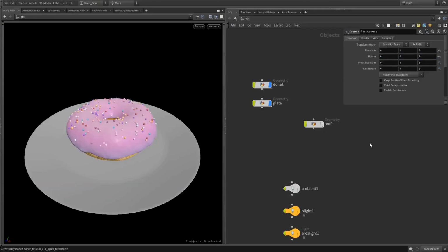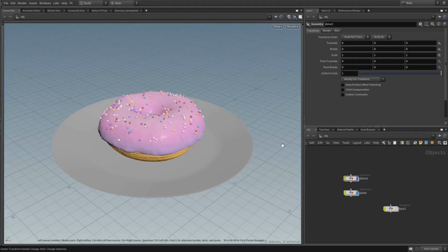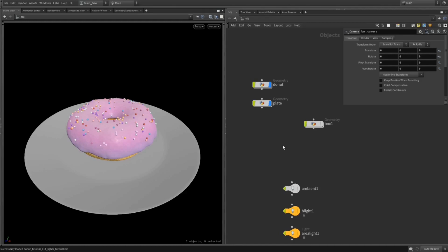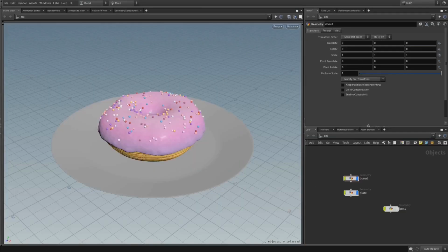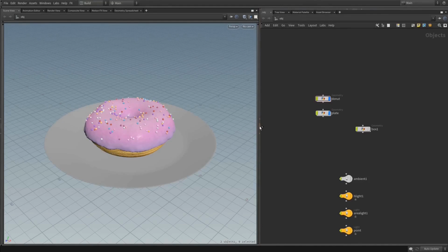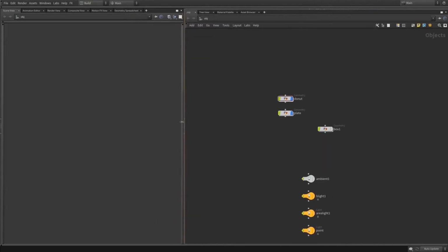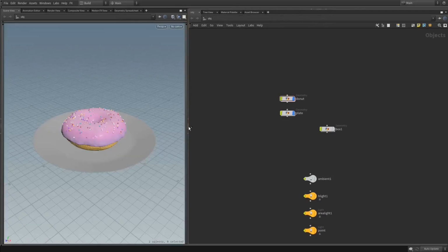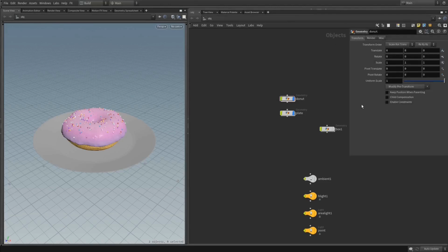Now in this section we're going to learn how to customize Houdini to look like this as opposed to this where we left off, so we can both be on the same page. As you can see, there is a little arrow that you can click and that will collapse the panel like you have seen. Now this small handle on the UI allows you to change it like this, or if you middle click it, you can switch between these two panels. Also you can alt middle click it. Also when you have done that, we will press B to bring back that parameters panel, but now we have it as a subsection of the network editor.